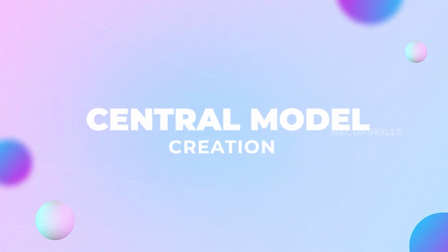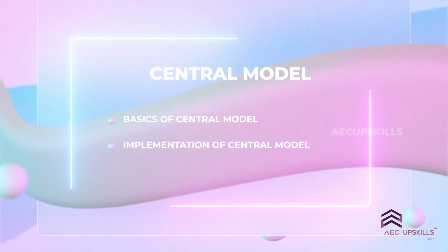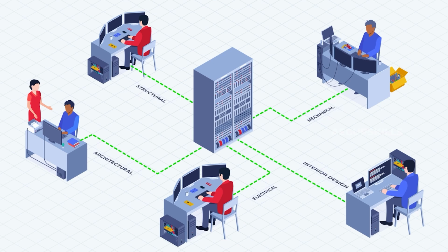This session, we are going to create a new central model. Now, before we go into central models, we have to understand its importance. In Revit, multiple people work on the same file simultaneously. This is accomplished by utilizing the central models and the local files.